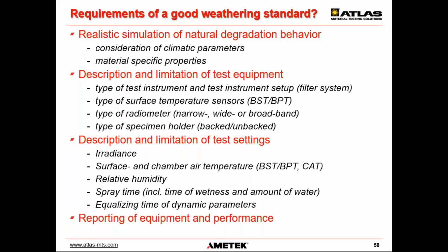Material-specific properties should be evaluated. The description and limitations of the test devices should be specified to include the type of test instrument and the test instrument setup, which tells you which filter system, the type of surface temperature sensor, either black standard or black panel, the type of radiometer, either narrow, wide, or broadband, the type of specimen holder, either backed or unbacked.